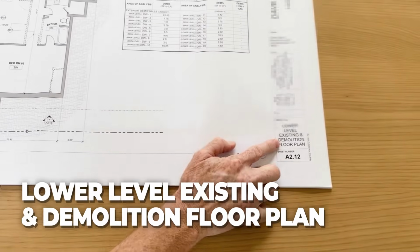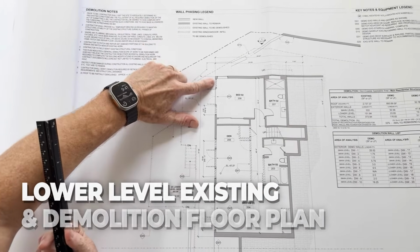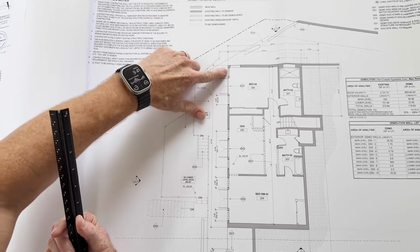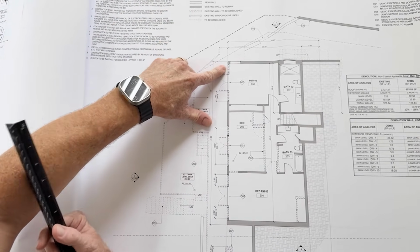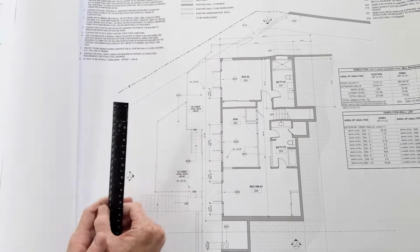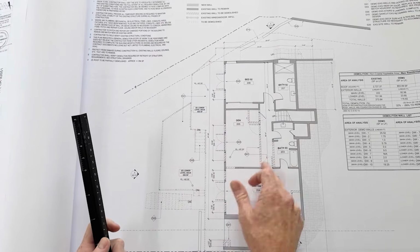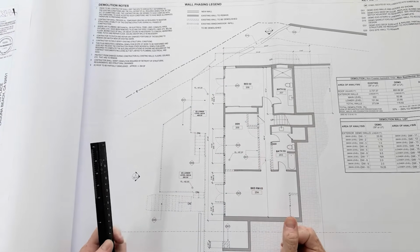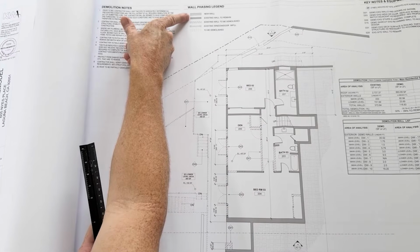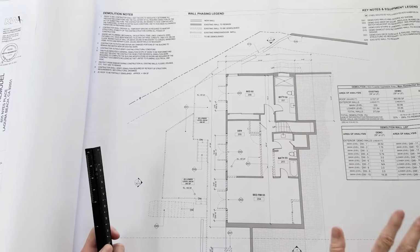Demolition floor plan. You can see very clearly here, these walls are to be demoed out. So anytime we have a hash mark here, existing wall to be demoed, we demo it out. What I like to do a lot of times, specifically as it relates to demolition, is I'll go through and highlight these with a highlighter to determine exactly and not get confused with what gets demoed out. These dark gray walls indicate they're to remain, all right? So we don't want to take those out. So anything that's dark gray, we're going to keep exactly how they are.